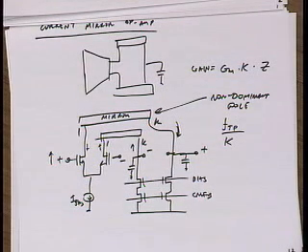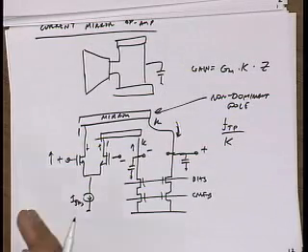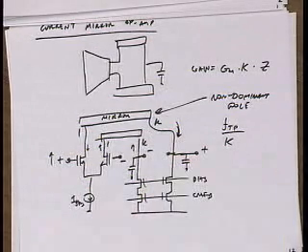It's the dominant one. But in terms of design, right? What are you limited by? If you try to make this higher and higher speed, at some point you run into a wall, right? That wall is a non-dominant pole. So which case is going to give you a higher non-dominant pole? Yeah, it's with the PMOS input. Yeah, because now you have an NMOS mirror.